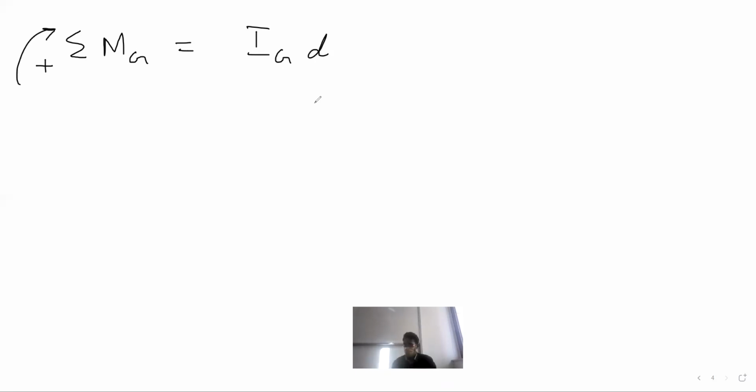Now, okay, who was the student who told us find the moment of inertia first? Who said that? Daniel. Daniel said that. So let's use Daniel's strategy. What is Ig? So right now you have to Google it. Google the moment of inertia about the center of mass for a thin slender rod and tell me what Google tells you. I actually know it right from the top of my head, but you have to do it in your free time. Open even a Wikipedia page, find it for a thin slender rod. You will see that Google will tell you that Ig is equal to 1/12 ml square.